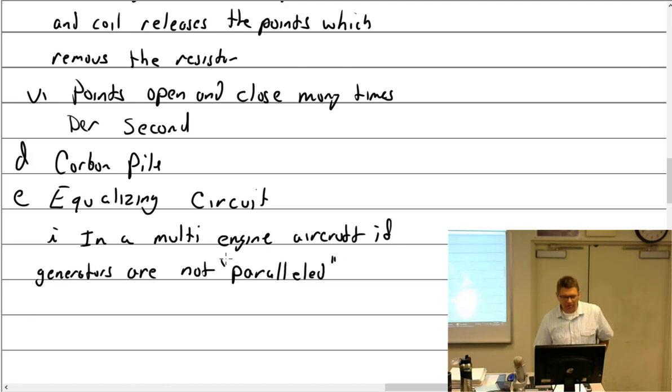and paralleling a generator is something you do as a mechanic. Whenever you change out a generator or a voltage regulator or any of the charging components on a twin-engine aircraft, you've got to parallel them, following the manual. You run up the engines to a certain matching RPM, and you fine-tune and adjust the voltage regulators to a point, and there's usually an equalizing circuit built into the middle that fine-tunes it even further on its own, like a third voltage regulator.